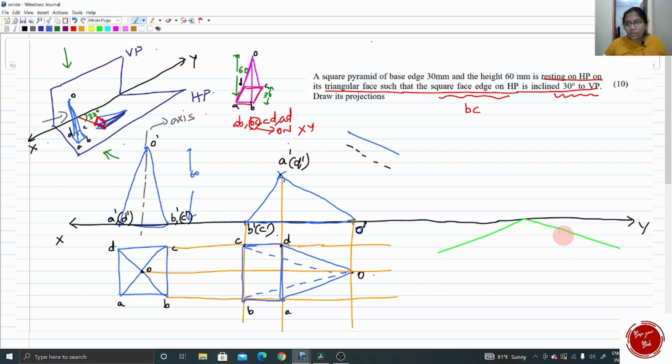So if I draw CB along this way, this is your C and this is your B. Okay, I am turning the CB in this direction. So CB becomes on this line, and everything else will be over here. That is, above C you have D. So here becomes your D, and here is your A, and everything will cross XY and it will look congested, isn't it? So better that we choose this line to draw our CB edge.